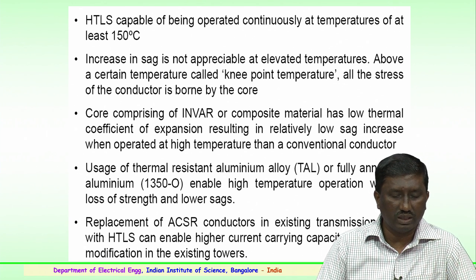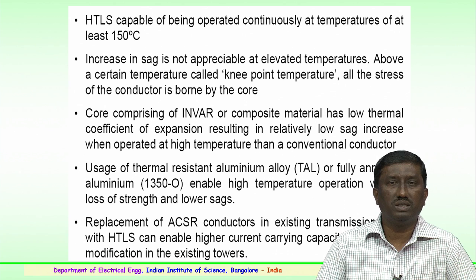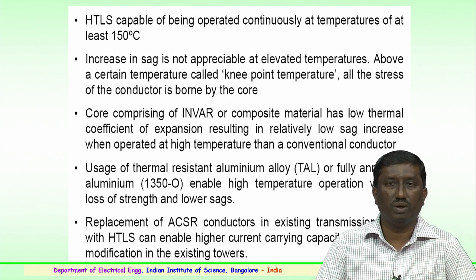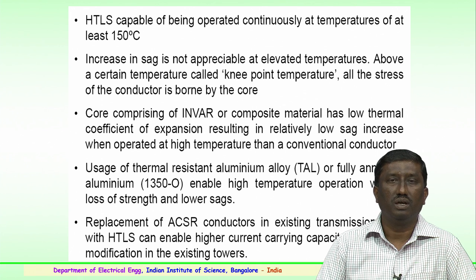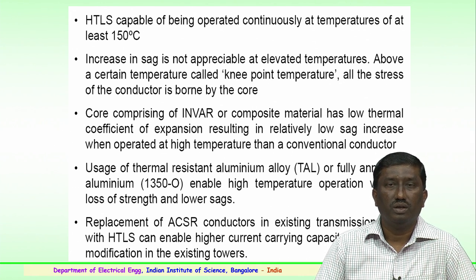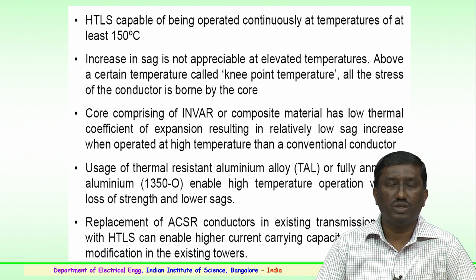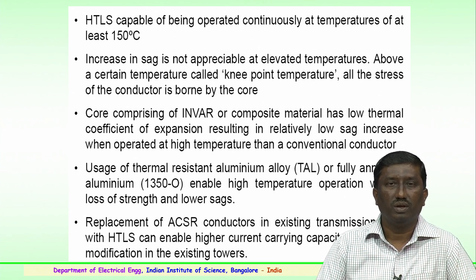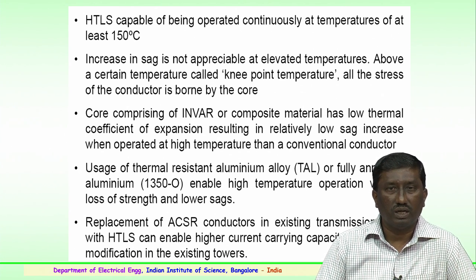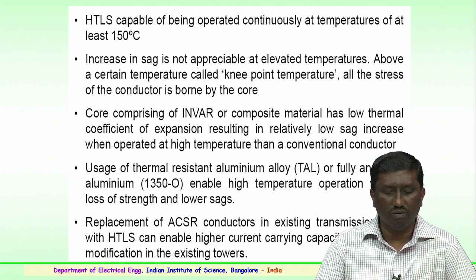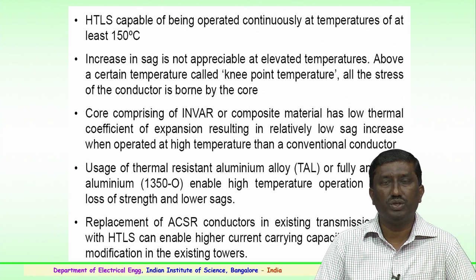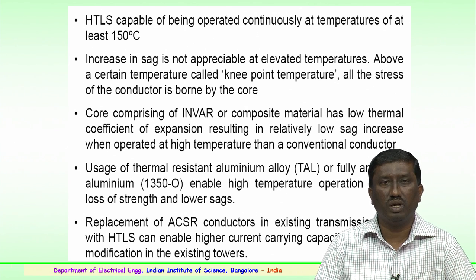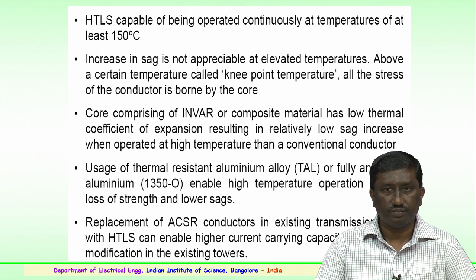So, in these conductors the increase in sag is not appreciable at very high elevated temperatures between 150 to 200 degrees. Above a certain temperature, which is known as the knee point temperature, all the stress of the conductor will be borne by the core, that is the characteristic of the conductor. The core of the conductor, basically comprising invar or a composite material, has a low thermal coefficient of expansion.